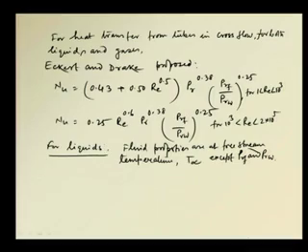As we understand, Pr_F and Pr_W are to be evaluated at T_F and T_W, that is the film temperature and the wall temperature.